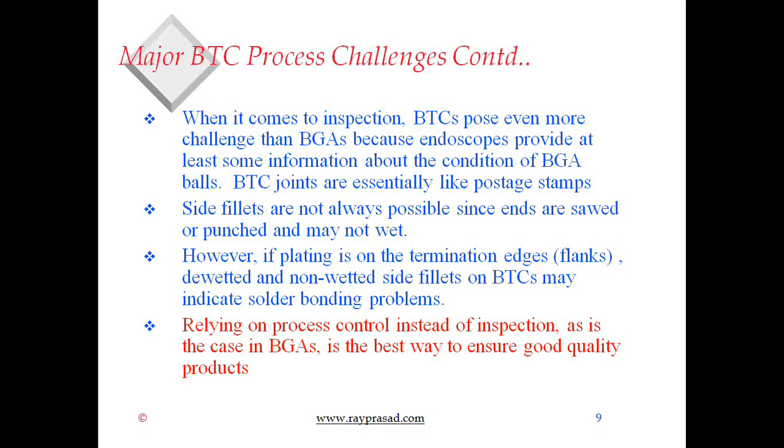So when you're getting into these kinds of devices, you basically have to depend on in-process control. What that basically means is that when you get into this technology, you develop the process, have the right design, do the X-ray, do the cross-section, and see what process recipe, what design recipe is giving you the quality that you need. That's your best guideline about how to proceed. So I want to emphasize some of the top-level issues here before getting into that.